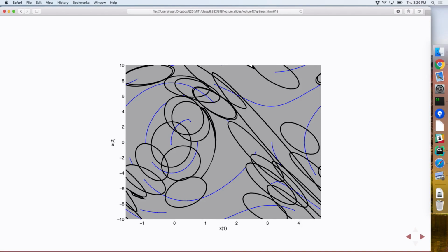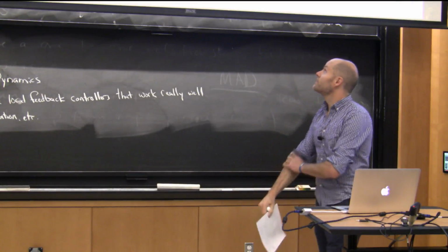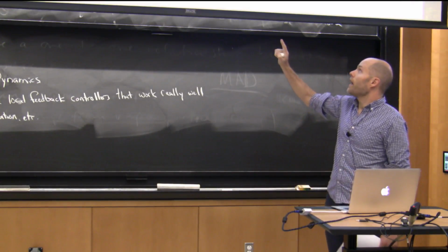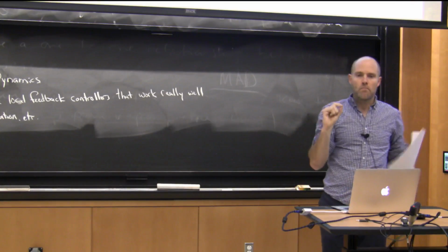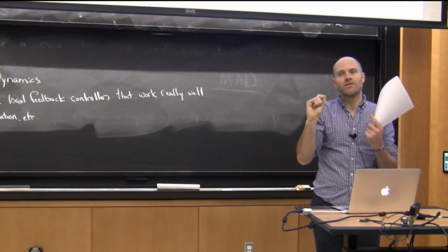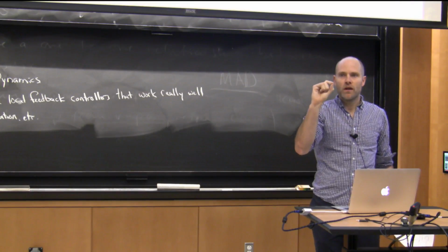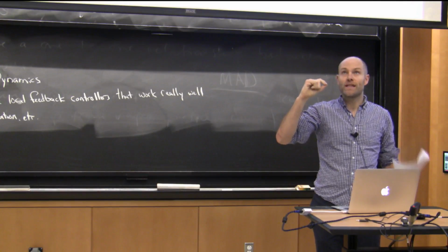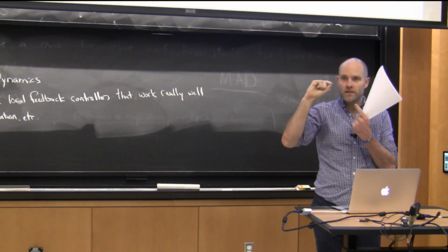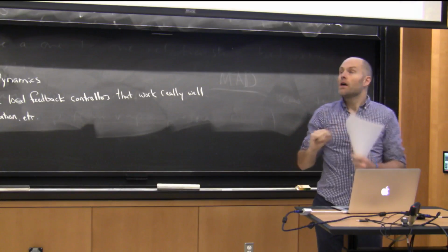Yeah. How do you know which node on the tree to aim for with the trajectory? Good. We can get into arbitrary levels of detail there. This is different than the RRT in the sense that the RRT banks on the fact that eventually it will sample close enough to the tree that a trivial extend operation will work, okay? So you can get away with even having a Euclidean distance metric and trivial extend operations which just go forward.